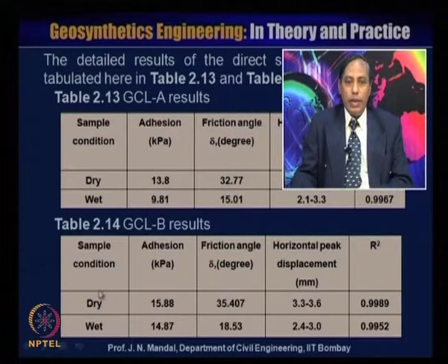You can see, whether it is a dry condition or a wet condition, the adhesion factor is 15.88 kilopascal for dry and 14.87 kilopascal for wet. The friction angle is 35.407 for dry and 18.53 for wet. Then the horizontal displacement for dry is 3.3 to 3.6, and for wet it is 2.4 to 3.